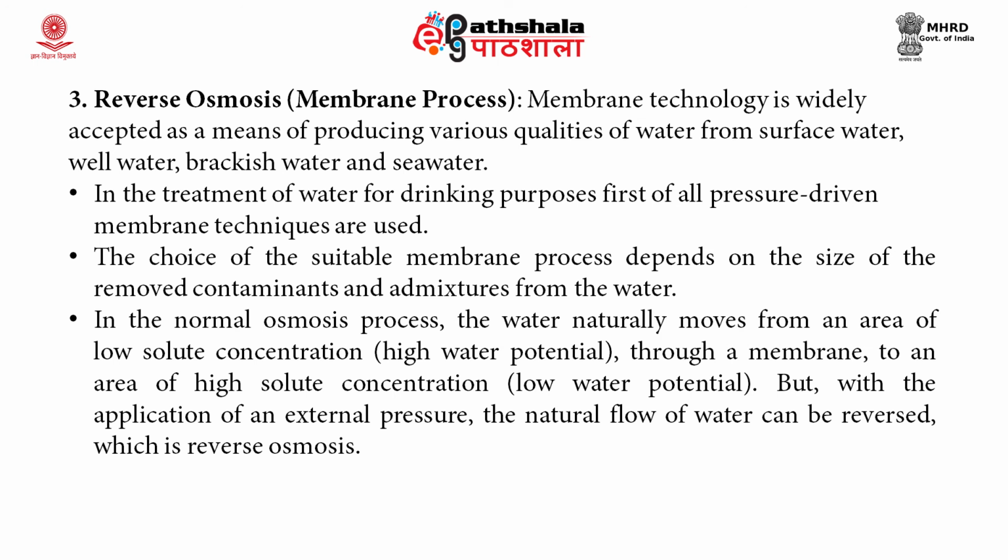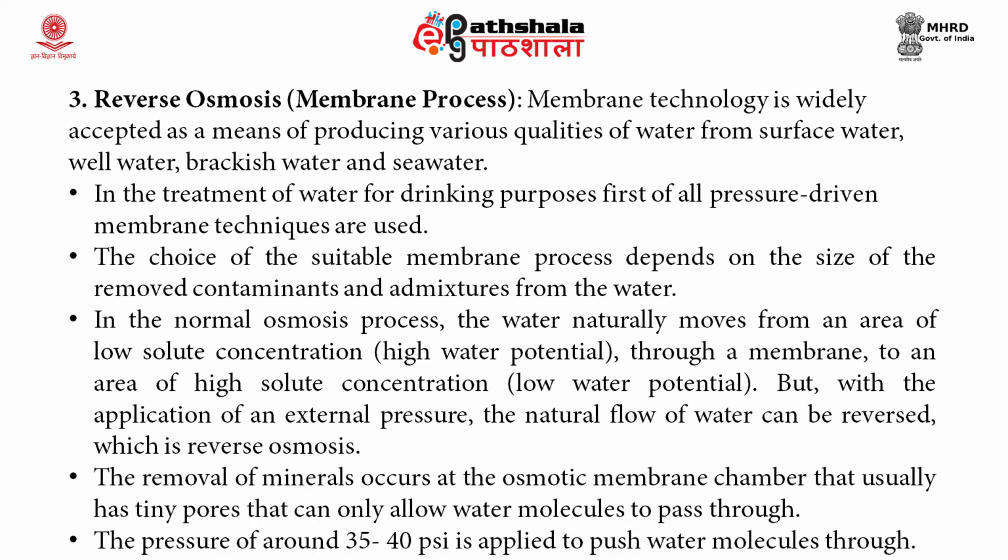In the normal osmosis process, the water naturally moves from an area of low solute concentration through a membrane to an area which has a high solute concentration. But with the application of an external pressure, the natural flow of the water can be reversed, which is nothing but reverse osmosis. The removal of minerals occurs at the osmotic membrane chamber,